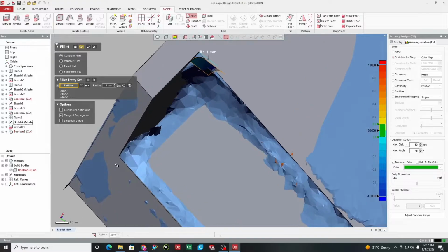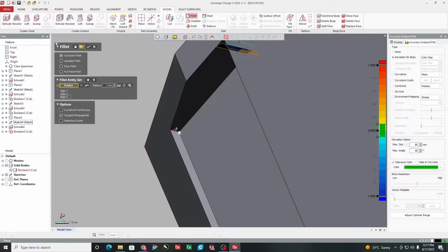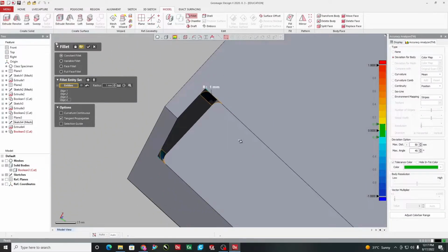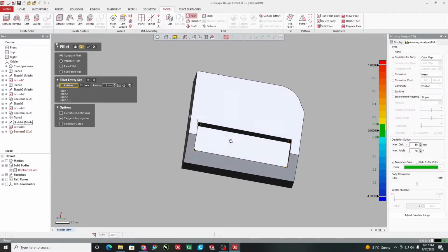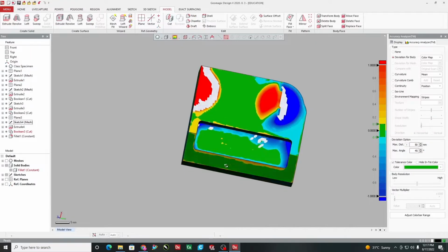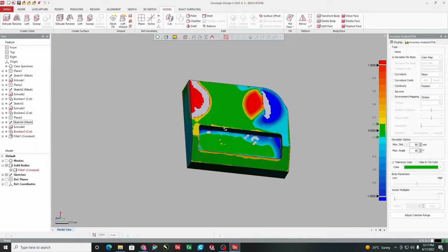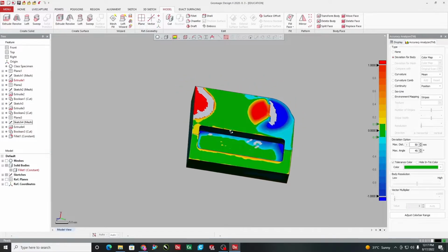So we can hide them, as sometimes the corner is not, we are not able to select. So okay, now we can select the corner. We have hidden the original object. So these 4 fillets are now put here, all with 1 mm dia. These pockets are now generated. These fillets are generated and the pocket is now complete.